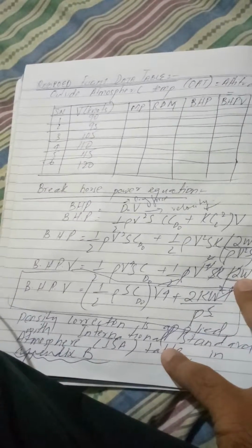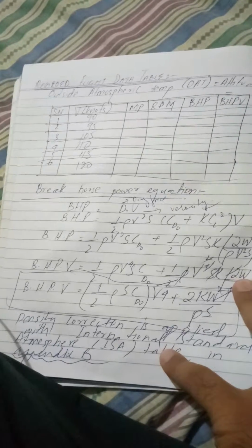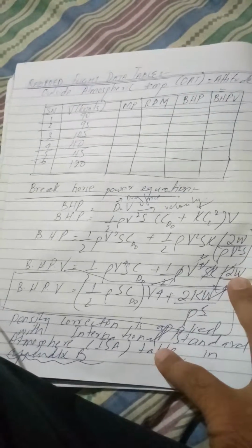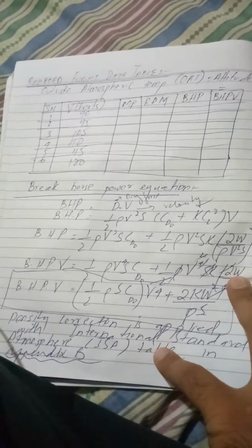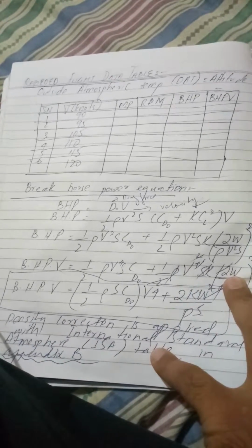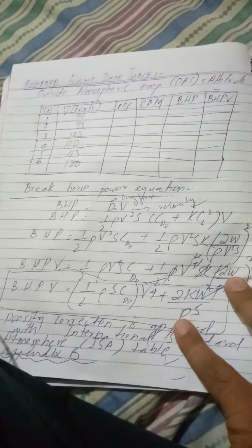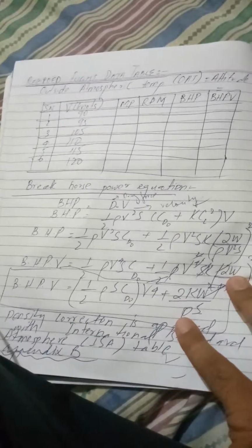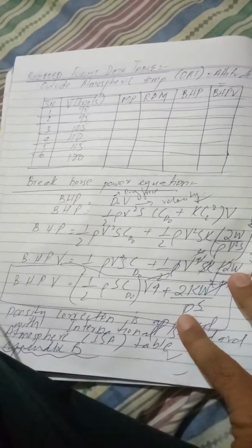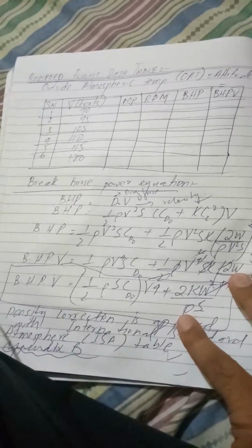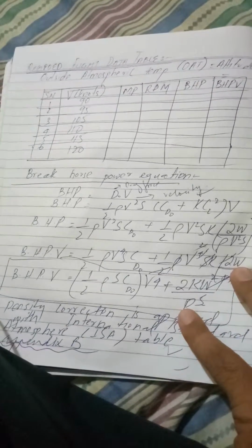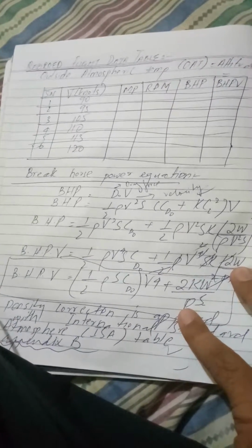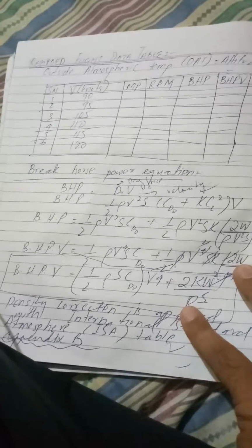V is in knots, MP is manifold pressure, RPM is revolutions per minute for the engine, and BHP is what? Brake horsepower, and BHP when multiplied by velocity we get the other values as well. So we plot the values, and we get the relationship in terms of slope and intercept, with the drag coefficient as well.